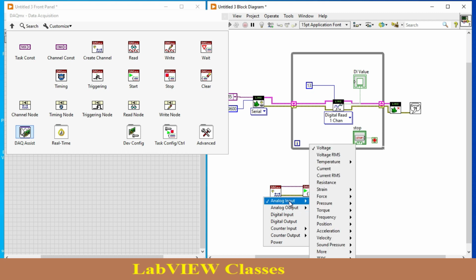On third party hardware, like we have the Arduino board, we have different hardware available in the market, like NodeMCU. Have you heard about NodeMCU? ESP32. Okay, on these hardware devices there is no analog output port, but in every NI DAQ card there are two analog output ports.